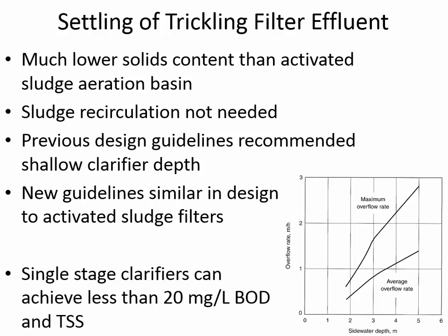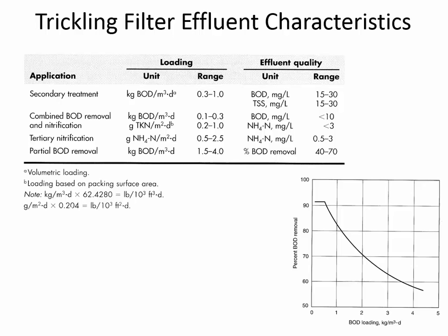particles begin to settle. And you can see in the text there's an upper range and a typical range of overflow rate versus side water depth, and that's how tall the clarifier should be in order to get the solid particles settled out before removing the water off the top of the clarifier.